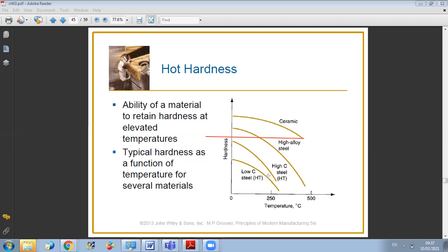So as temperature increases, the hardness is reduced dramatically. So you can reach a very low hardness at high temperature. Okay. And now, in case you want to have a final product with higher hardness, what you can do is implement to steel a higher percentage of carbon. So you can see here that for high carbon percentage in steel, you can reach better hardness than the low carbon content.